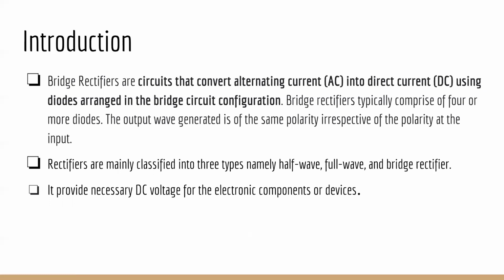It is commonly used for high power applications because it has the highest possible transformer utilization factor for a three-phase system. A bridge rectifier can be constructed with four or more diodes or any other controlled solid state switches. Depending on the load current requirements, a proper bridge rectifier is selected.